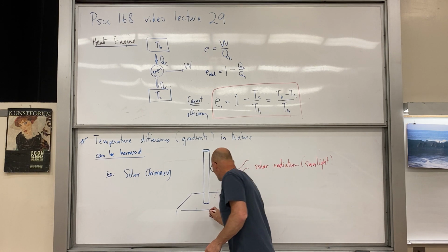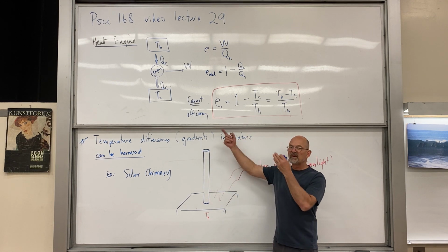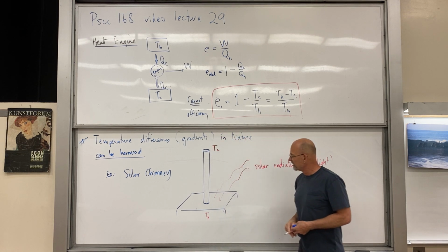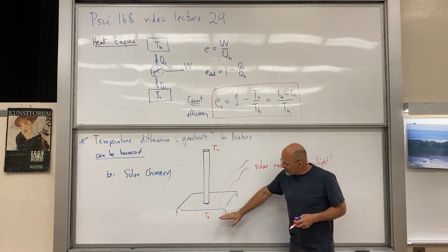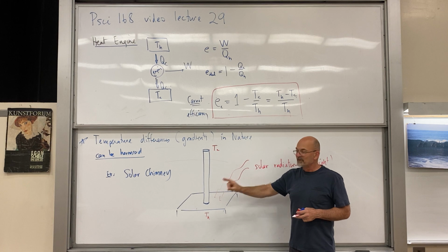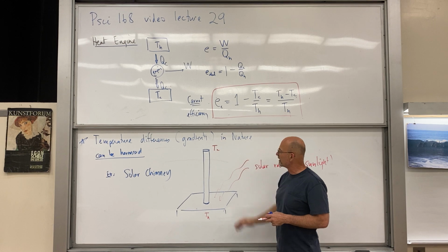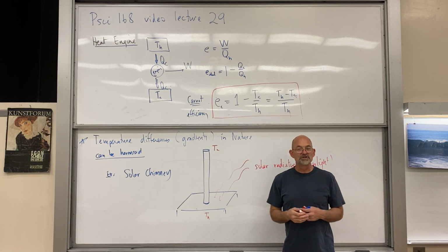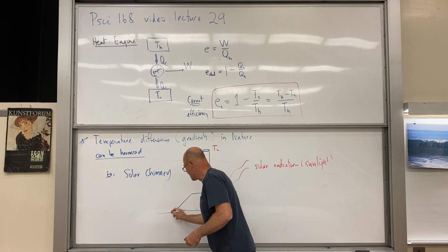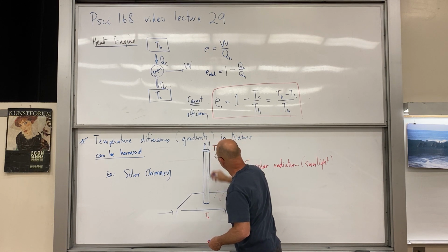So what does that mean? It means we have a higher temperature air down here, and the chimney's as high as you can make it. And up here we have lower temperature air. So there may have been a natural difference in temperature between the ground and somewhat up off the ground, but what we've done is we've increased that natural temperature difference. So now we have hotter air underneath, cooler air on top, and that's enough to set up a chimney effect, the convection. So now we have, since the sides are open, air coming in from the side being heated, going out the top.